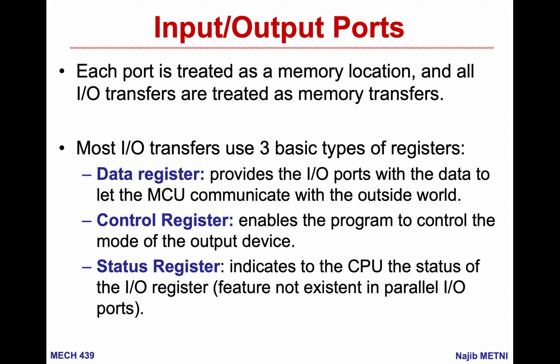And this is a very important feature in order to optimize the price and the pin count. For example, maybe I will buy a microcontroller for 2 applications. In the first application I am using 16 inputs and 1 output, and in the other application I am using 1 input and 16 outputs. I will not be obliged to buy 2 microcontrollers. I will buy just one, and I will change the control register by setting 0 for this pin to be an output and 1 for this pin to be an input. And I will tell you how in Arduino we can do this.